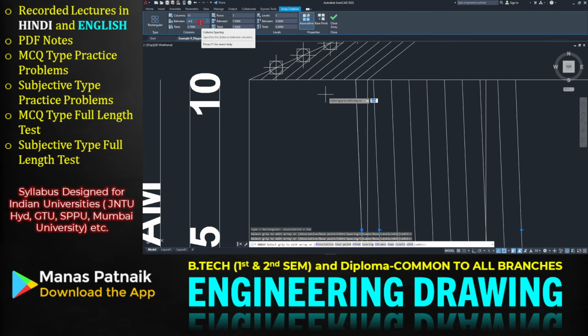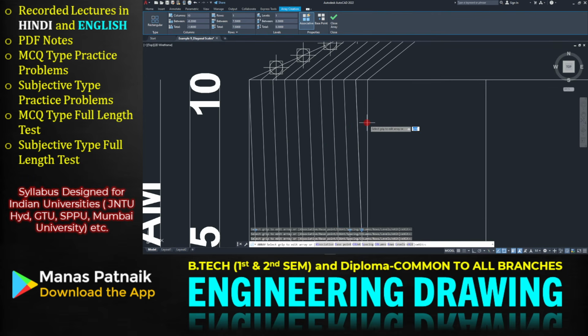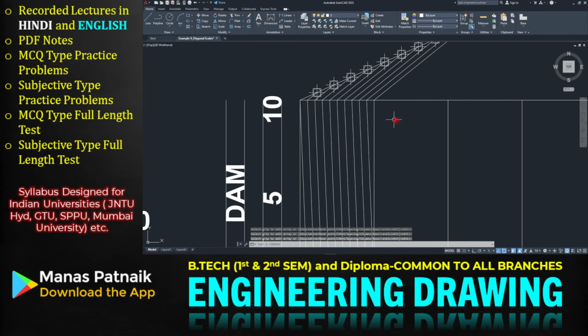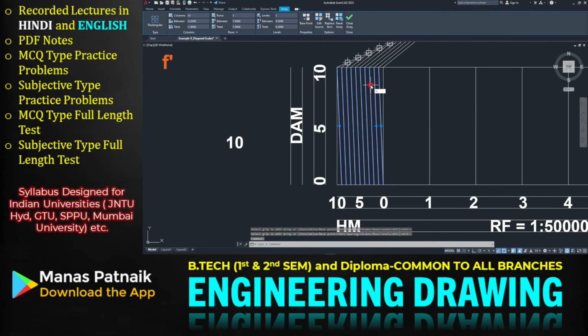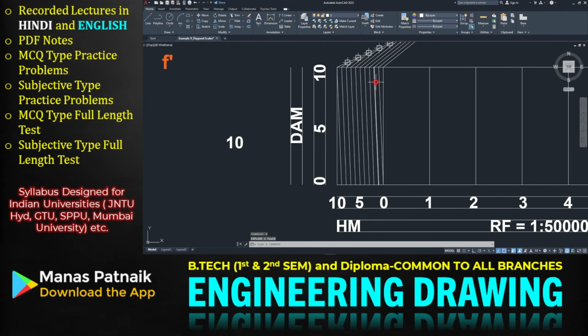0.2 and then enter, and you'll see all of these rectangular arrays will shift automatically to the left. Wonderful. Hit enter again and you are out of the array command. Now what we can do is simply click on this, hit X, enter, and all of these have been converted to their individual line elements.